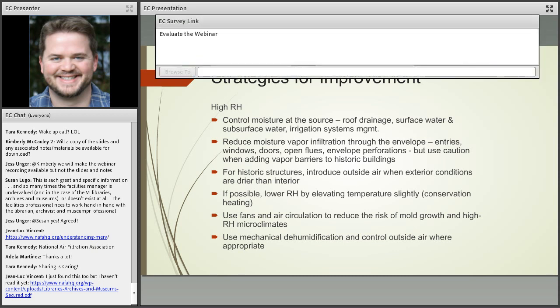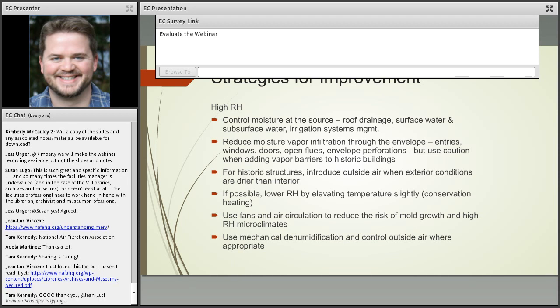In many cases, it's worth thinking about reducing your quantity of outside air brought into the building overnight, whether it's causing a problem or not, but really just to reduce that moisture load on the building and on the system. If you're in a particularly tough weather cycle right now, and I'm not sure where you're located, but I know on the East Coast, especially over the last month, Philly and New York have had a lot of problems with very high moisture contents.